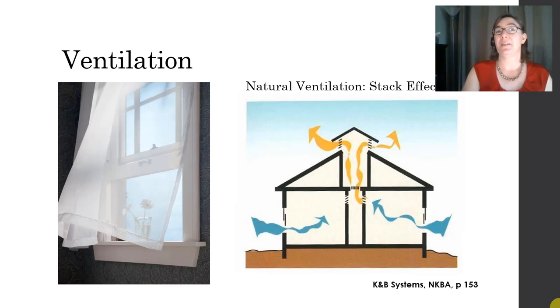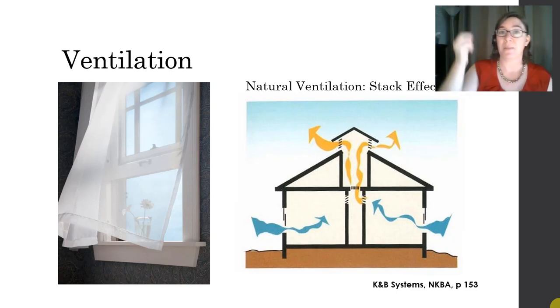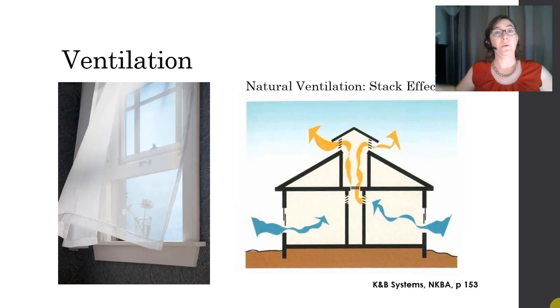Natural ventilation can be as simple as opening up a window in your home, but it can be a little bit more complex in design, based on the stack effect. This is the name for realizing that hot air rises. And so by providing a place for the hot air to escape from the top of your home, you are able to draw in the cooler, lower air and cool your home naturally.